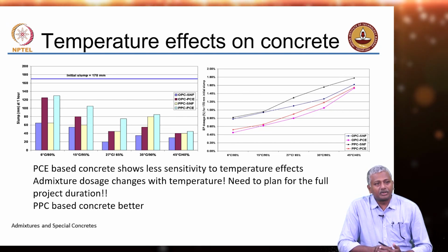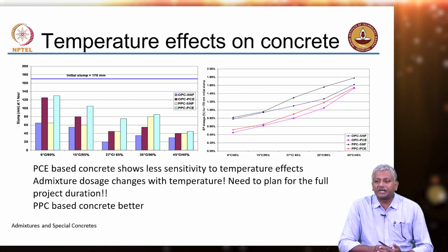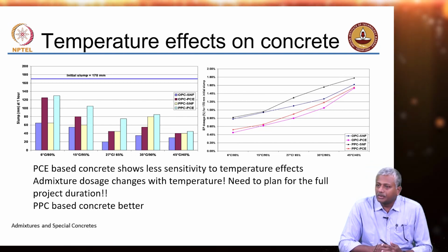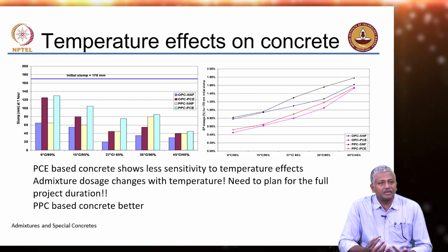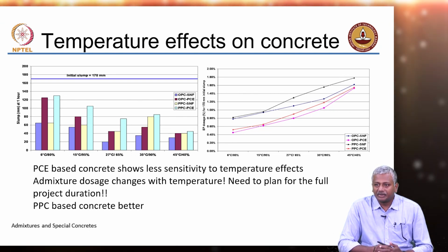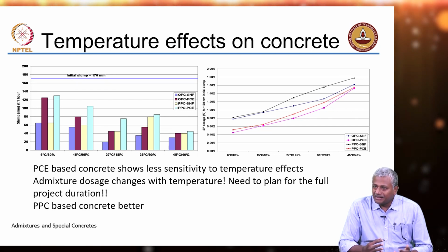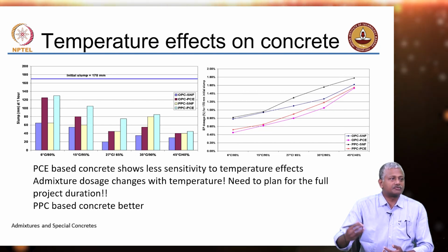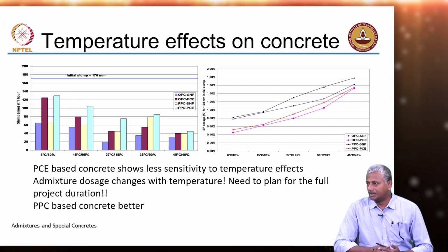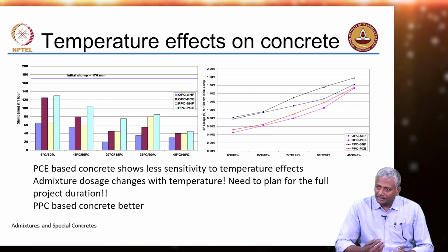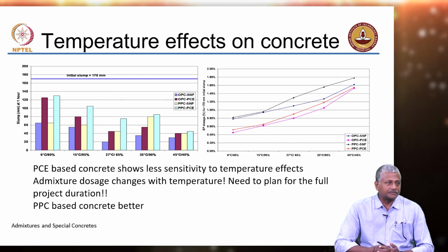In our laboratory we have a controlled environmental chamber which is large enough that you can actually move your concrete mixer into the chamber, condition your materials at a particular temperature and humidity, and do the test at the same temperature and humidity. The idea was to maintain the same weather conditions as you would expect in times of changing weather during a construction project. And we maintained that temperature for a period of 1 day and then shifted the specimens to normal curing.